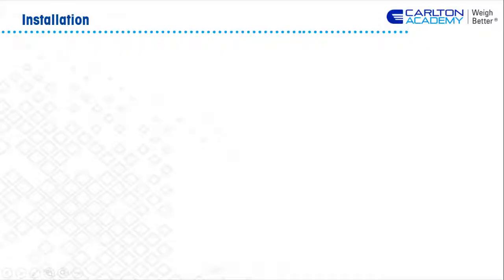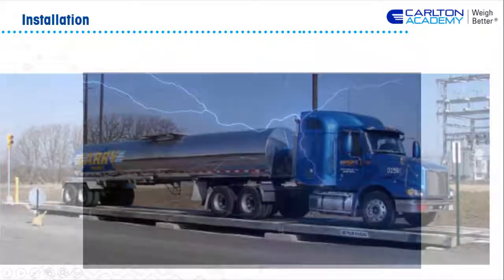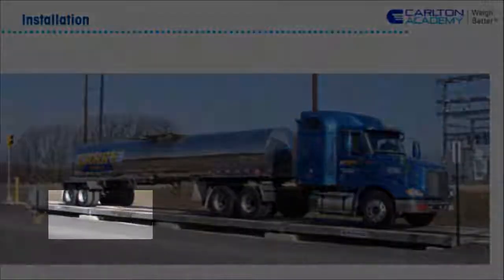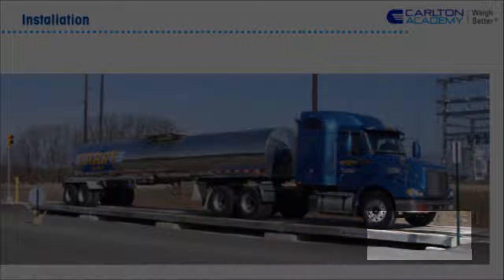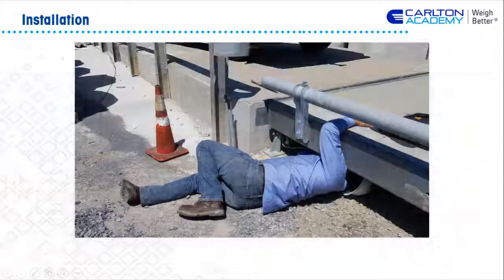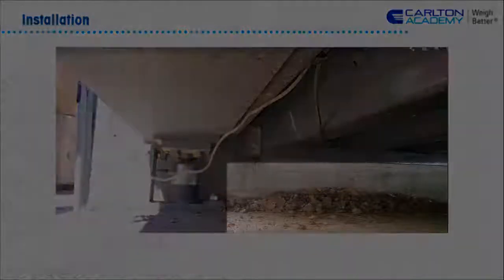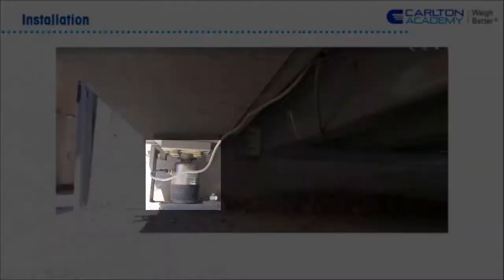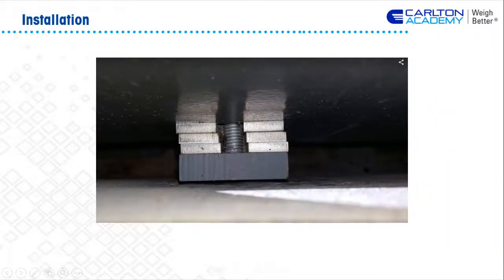Installation. If the equipment, such as the terminal, is installed out in the environment, check that all cable glands are secure and that adequate protection is provided. Equipment must have clearance so as not to interfere with the scale throughout its weighing range. Inspect for debris buildup and that the inspector will have the ability to inspect without obstruction from weighing components.